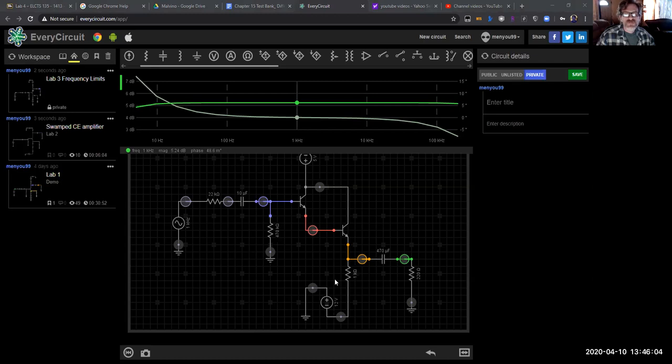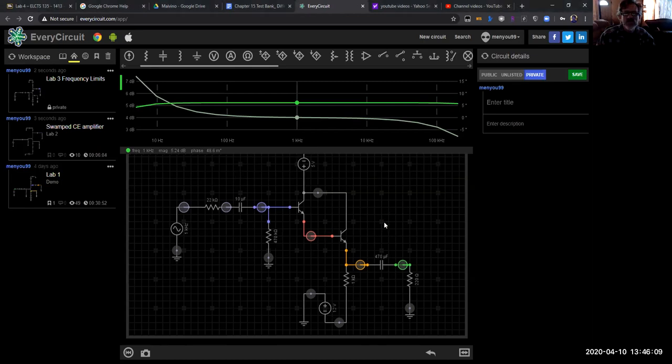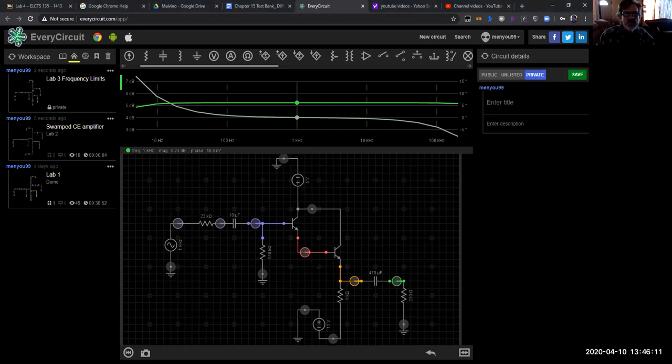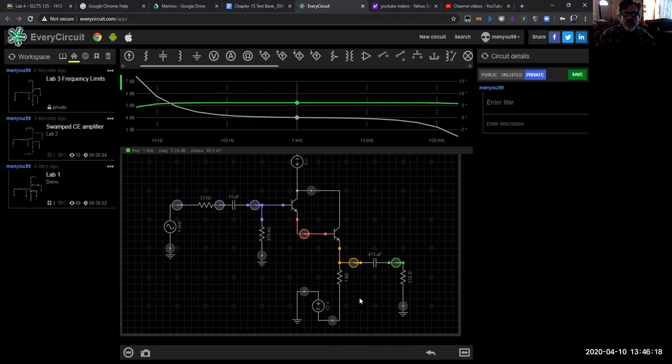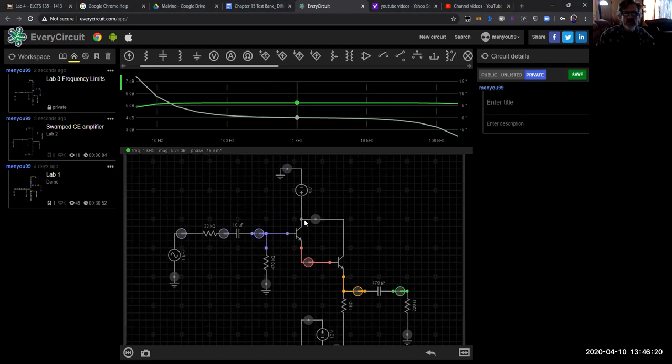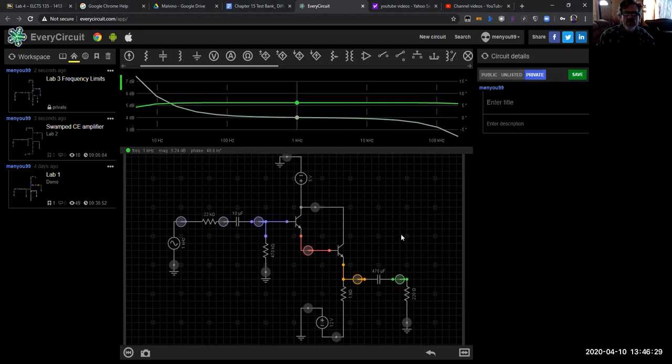And then, how would the circuit parameters change if a Darlington pair had not been used? Well, it's a very similar circuit to the others before. Basically, what did we do? We still have the negative supply in the emitter here, positive supply in the collector side, right? The only difference is we've added this one transistor in tandem with that. And you'll notice that compared to the swamped CE or even the CE, this circuit is far more stable.